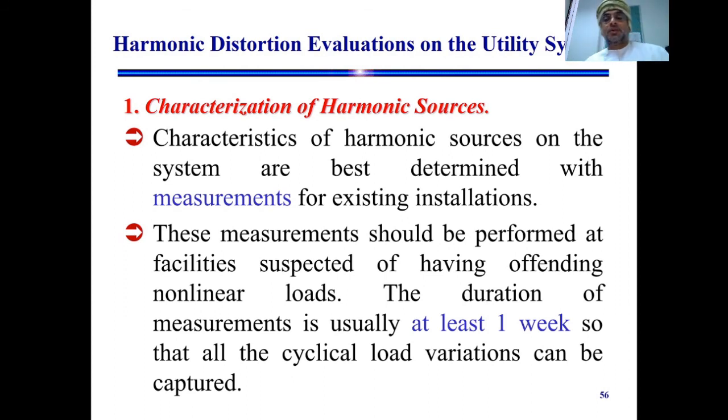Harmonic distortion evaluation of the utility system, characterization of the harmonics. So we need to take measurements, and this measurement has to be done for at least 1 week.